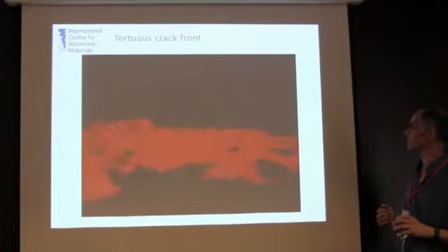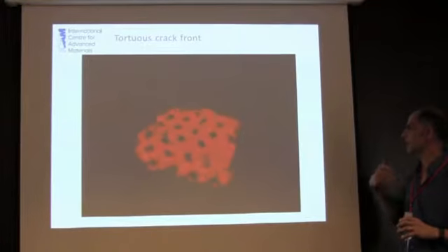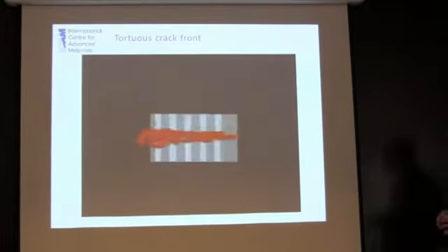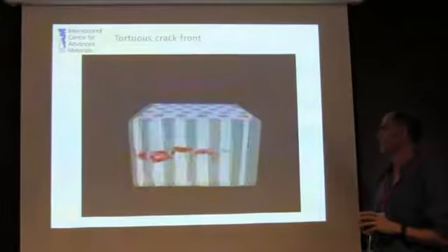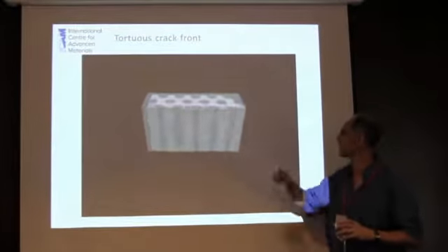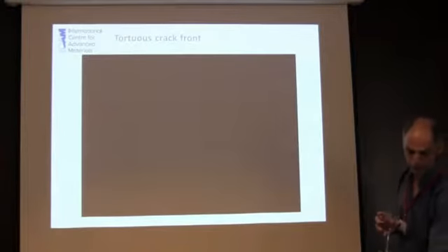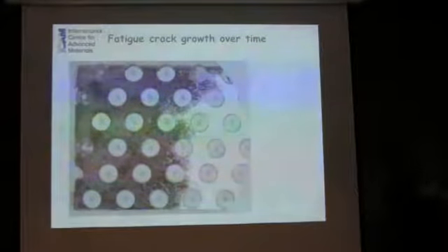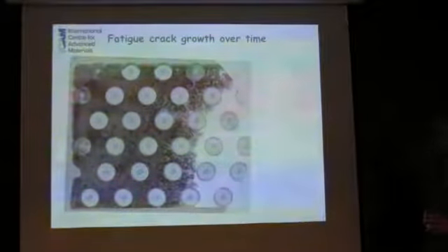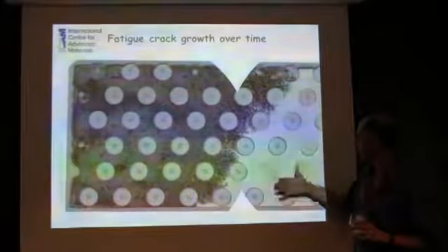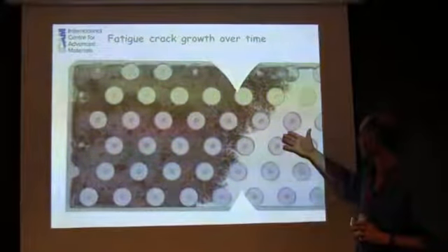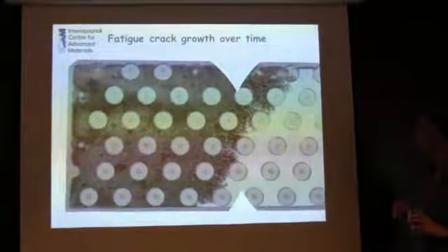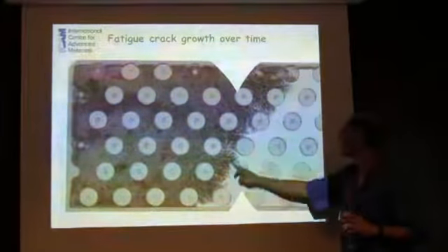So you can really see the three-dimensional nature of the crack and understand over a number of cycles how it propagates. And you can measure the crack opening displacement directly from that in 3 dimensions. You can see the crack opening there, and you can see the bifurcation of the crack. So, as I said, in this particular case, you can see the crack growing. In this particular image, we've made the matrix transparent, we've made the fibers transparent digitally. So it's as if you're looking through a glass fiber, glass matrix composite, and we can see the crack growing.